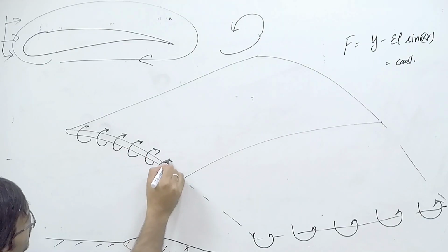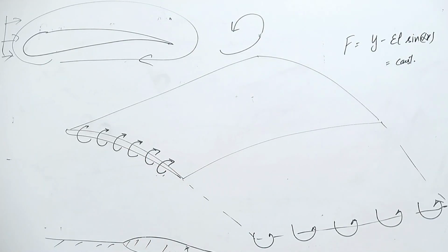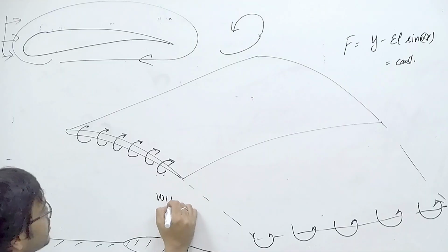So what is happening is that fluid is seeing this high to low pressure zone at the wing tips. So let's say this is your wing and this is how it is going forward, and this is your tip of the wing. There is a pressure that is higher on the bottom surface than the upper surface. So the flow actually turns from the tips in this direction, and these are what you usually call wing tip vortices.